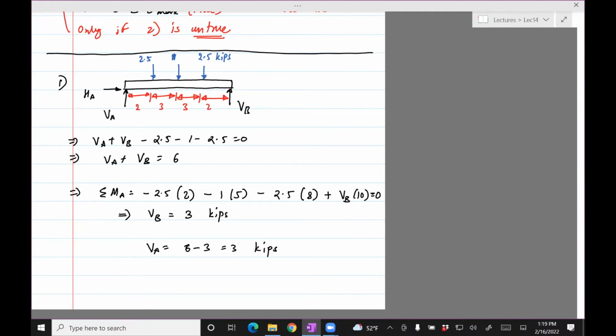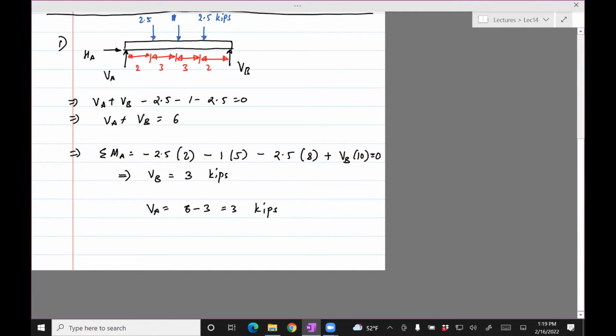So the moment I change one of those 2.5 to 3.5, you cannot make that assumption. But here, you don't need to do the moment equation. You can just do it from symmetry. So absolutely, if you write symmetric, VA should be VB, full points, no problem. I don't recommend this to people because then they may incorrectly assume things and get the wrong answer. It's always safe to do it this way. It's just that the first question we saw said symmetry, that's why.